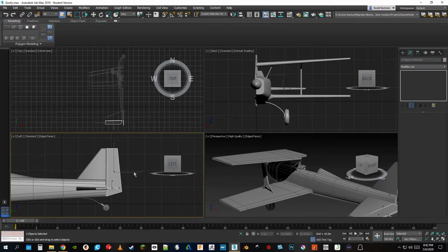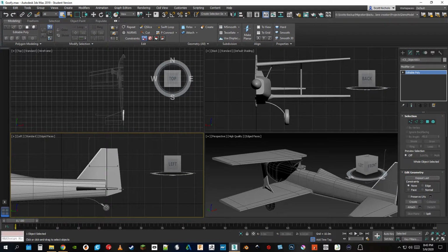But if we do it the other way, I can just run my selection through anything, and anything that one of these lines touch will now be selected. This button itself is not very useful because there's a way to set it up, and I'll show that to you some other time, where if I select going from my left to my right, then I have the window selection, so only things within my selection will be selected.